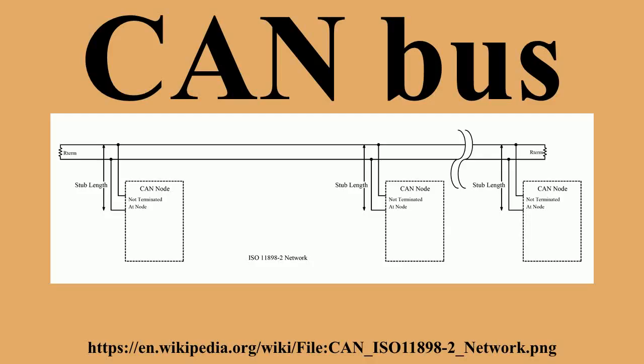Such non-standard wire harnesses that join conductors outside the node reduce bus reliability, eliminate cable interchangeability, reduce compatibility of wiring harnesses, and increase cost. The absence of a complete physical layer specification freed the CAN bus specification from the constraints and complexity of physical implementation. However, it left CAN bus implementations open to interoperability issues due to mechanical incompatibility.